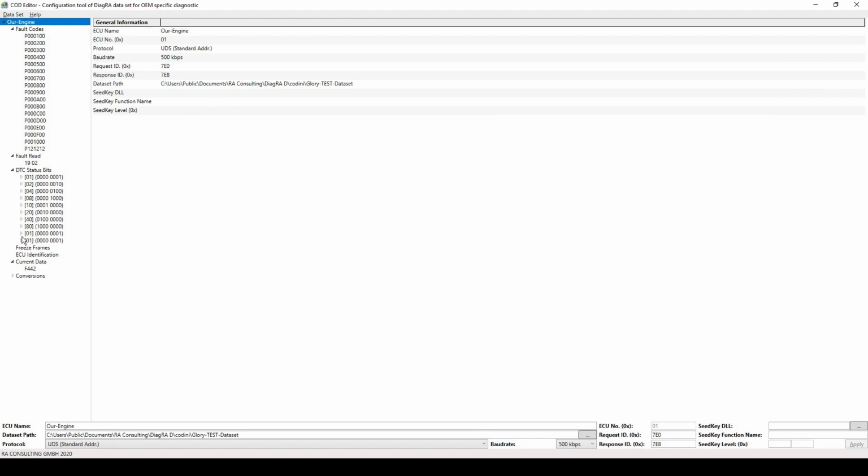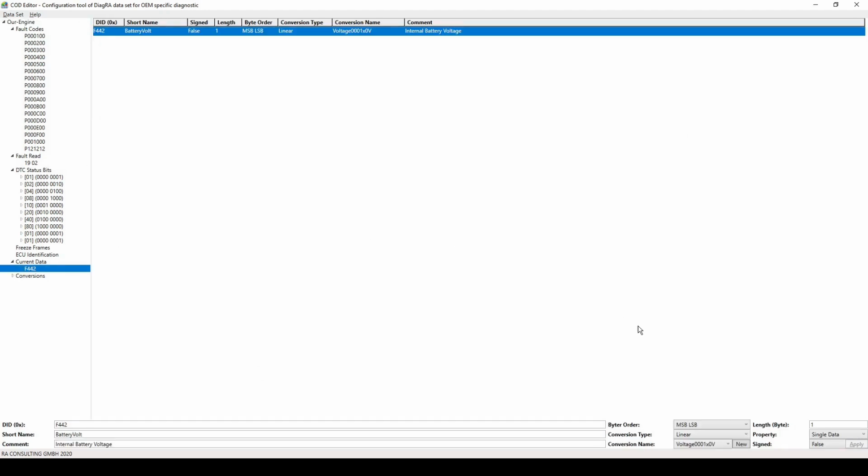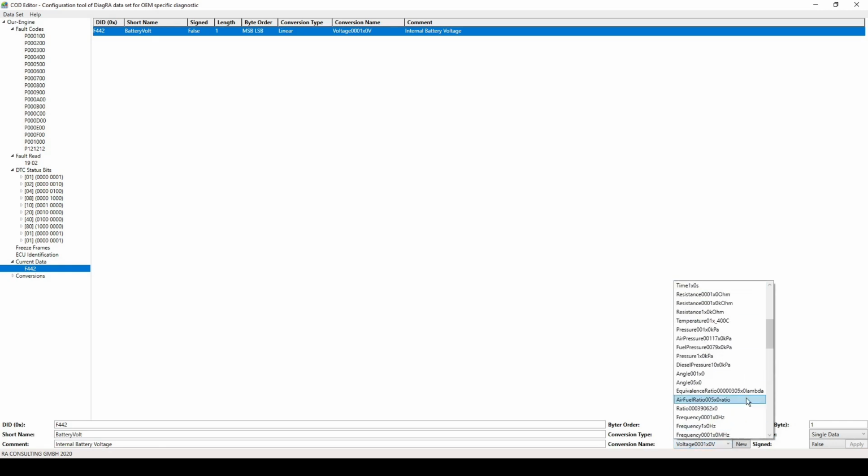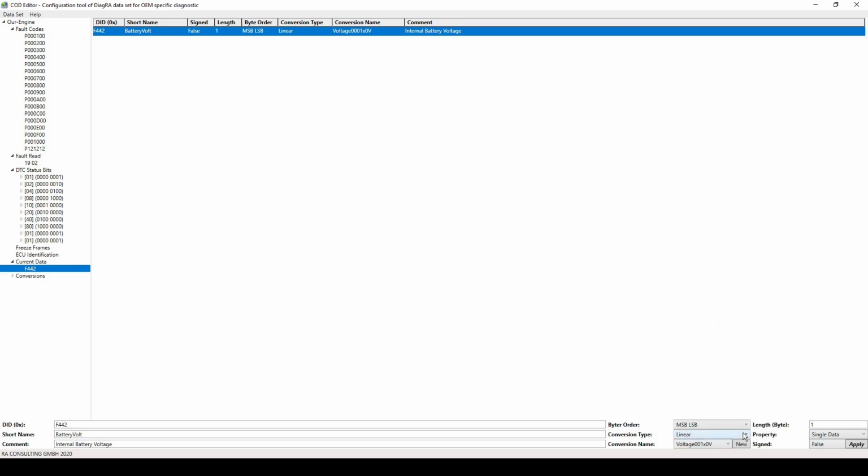We have a few options for voltage conversions here. Maybe it's possible we're using the wrong one. Let's try selecting a different one. That should do. And hit apply. Yes, this data is 2 bytes long, so that is definitely contributing to the problem. Make sure you have the correct data bytes length. Let's save this and give it another try.